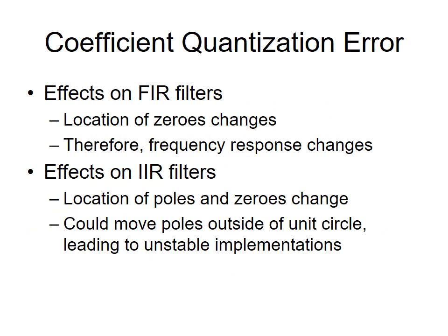Next is the coefficient quantization error. It means the effects on FIR filters and the effects on IIR filters. First, the effects on FIR filters: the location of zeros will change, and the frequency response of the FIR filter will also change.